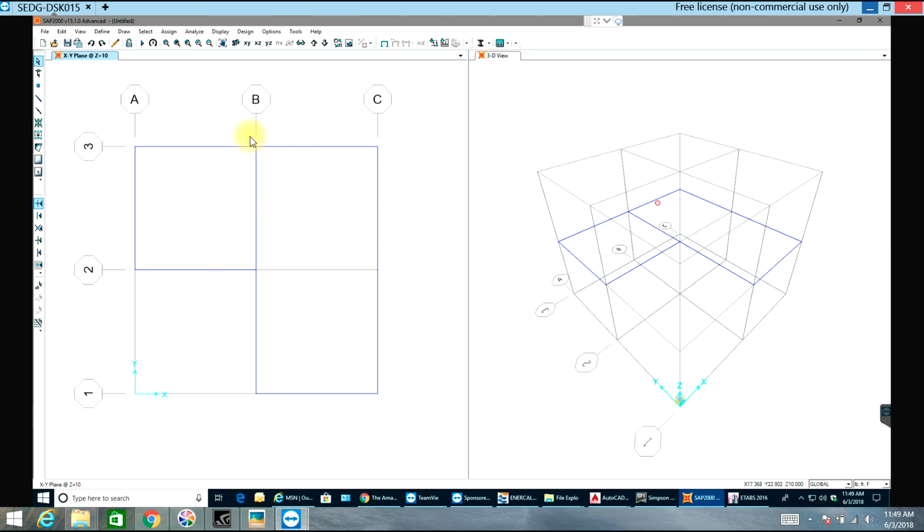Now that you have created this, oh, I need one more. I need from here to here, right? So now one more thing is we have a cantilever. Let's say it's a 3-foot cantilever on this side, and there's also a beam on this side, but we'll leave that beam for now. We'll just put this cantilever. So I'll just edit my grid data.